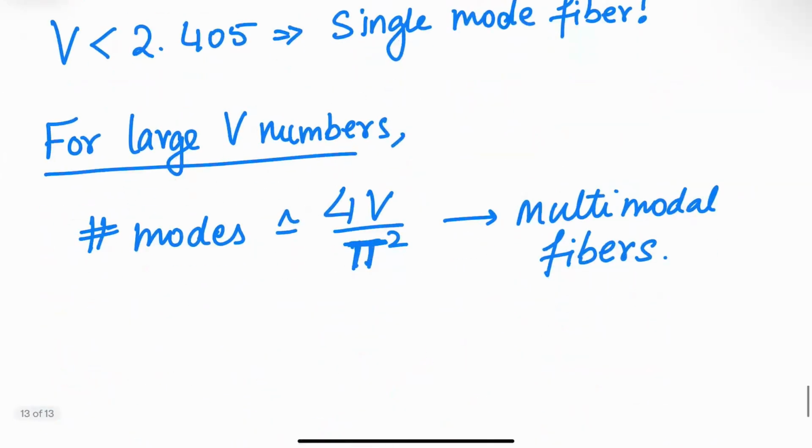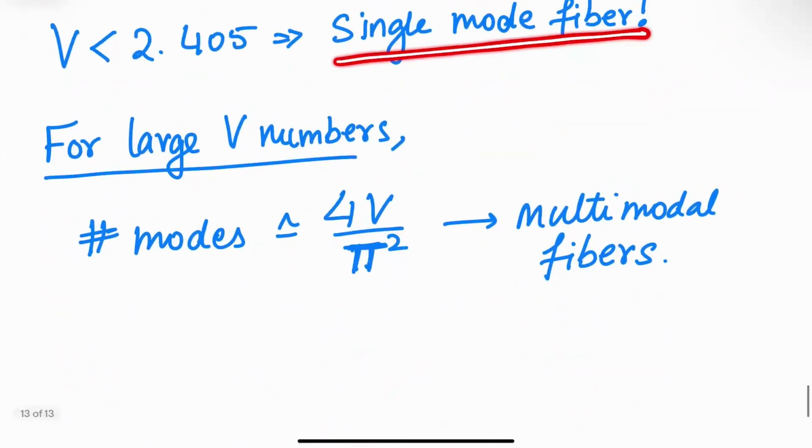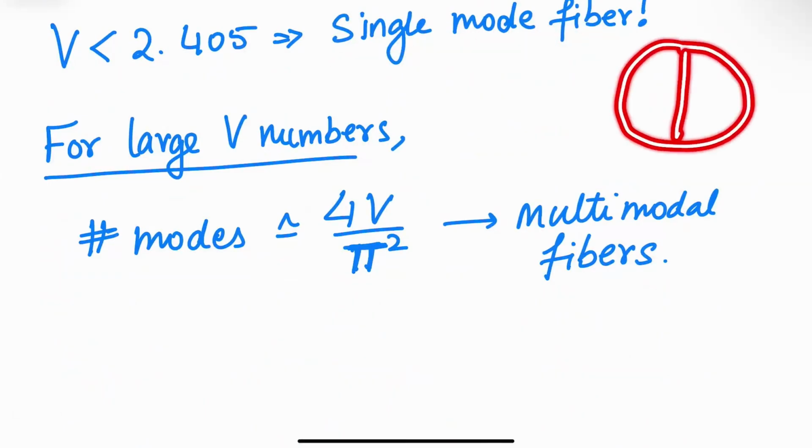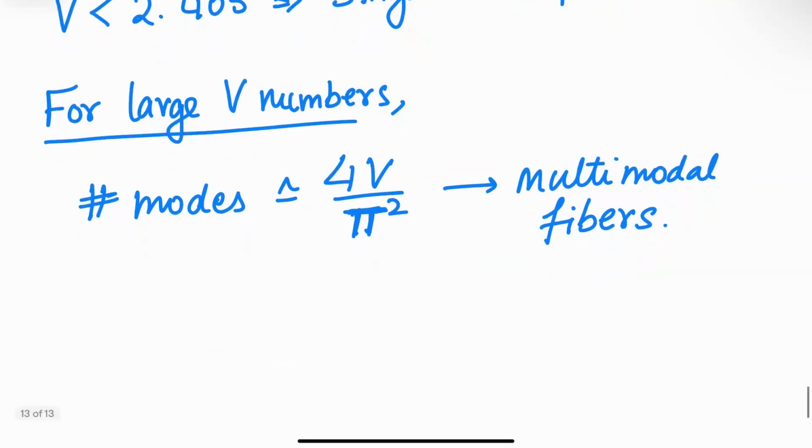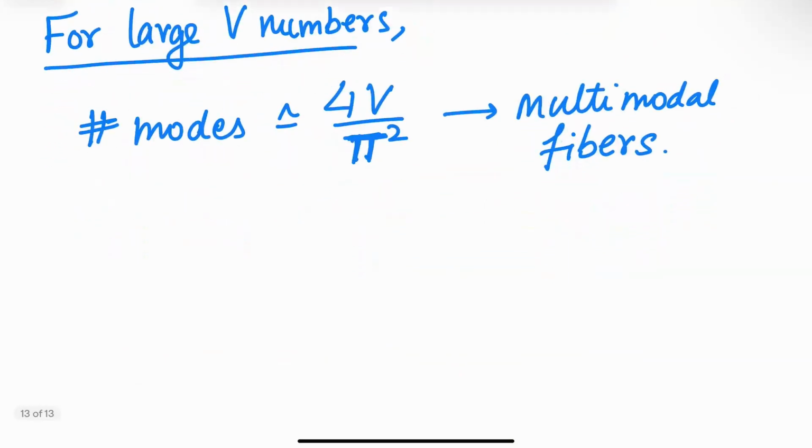Okay. So although we said that these are single mode fibers, in reality, every fiber has two modes, right? If it has this mode, two degenerate modes, then it also has this mode, just from the symmetry in phi, right? And these two modes are also degenerate, although they're orthogonal. And therefore, when you're propagating in a single mode fiber, if you want to maintain polarization, there is something called polarization maintaining fiber.